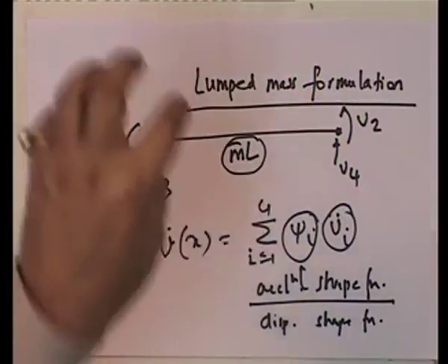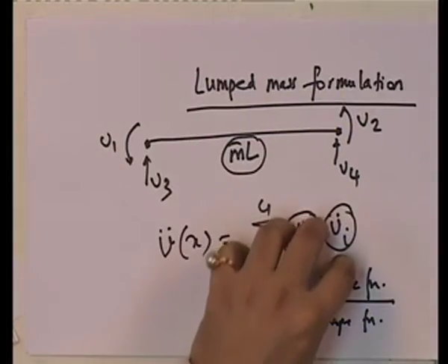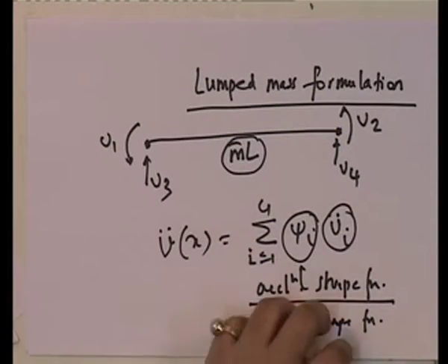And all that we are saying is that since we do not know what else to do with stiffness, okay, we will use the cubic Hermitian polynomials to develop the stiffness. Nothing wrong with that. Although again the K matrix that we get for solving a dynamic problem is approximate even for a uniform cross section, because we are saying that look, under the dynamic issue the xi remains the same as the original.